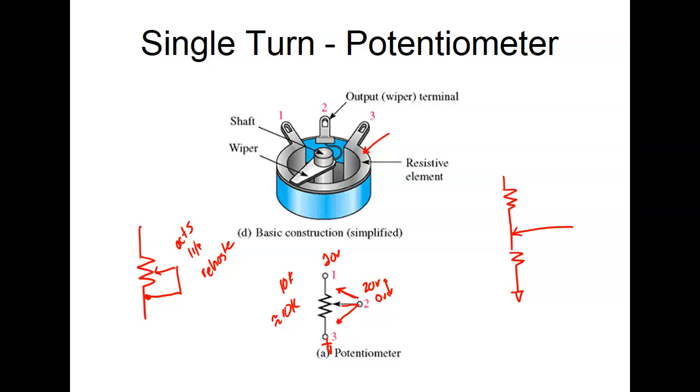Now what moves the wiper? A knob, or we can connect it to something, right? If I connect it to something, then the voltage that I get out would represent the position. So you're right, on ours we move a knob. On the trainers, if you use the variable voltage divider, you're setting the voltage with a knob.